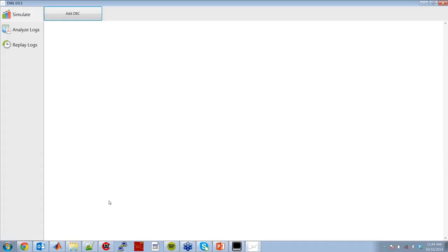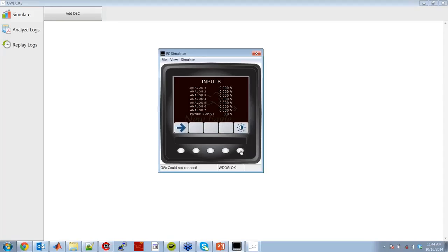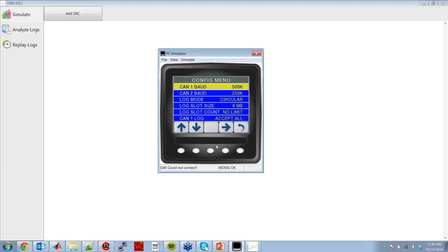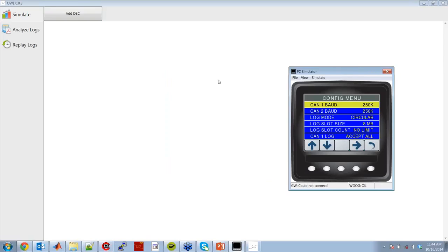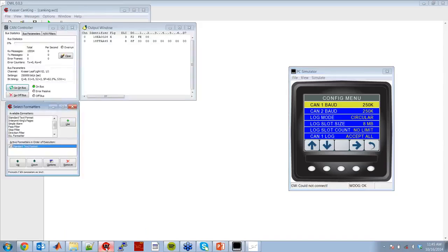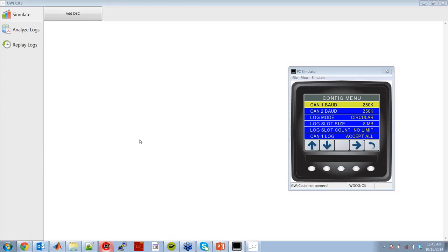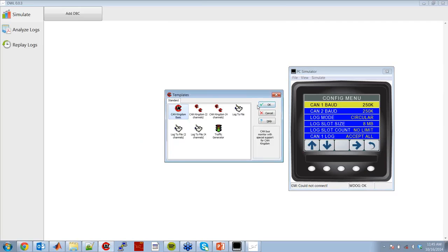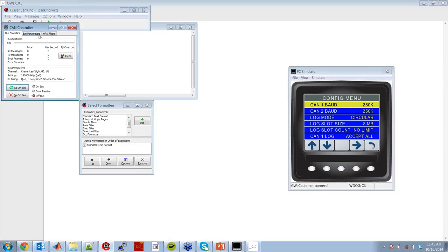You've got the menus that Steve showed in the simulator. Those show up on the physical display, and we've got one on the bench here. We'll use our CAN simulator to send out some CAN messages, manipulate the data, and then pull the USB stick out of the back of the display, put it into the PC, and then open the log and run it through the converter so that we can get some Excel data.